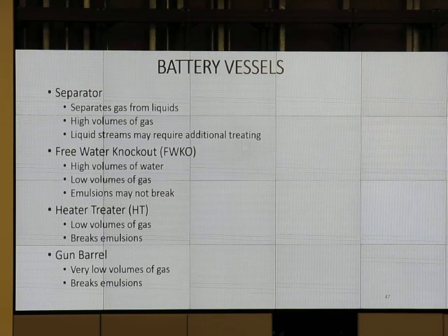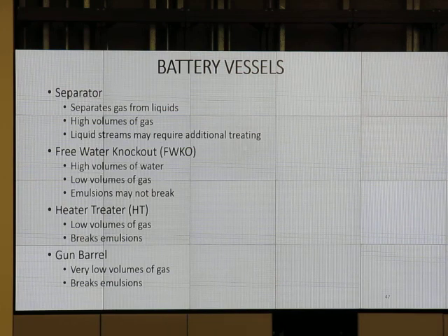A heater treater, and their other name is an emulsion treater, can handle low volumes of gas. It could be the primary vessel if the gas volumes are relatively low. And it's designed, though, to break emulsions. It's not a water handling device. It's designed to break emulsions.